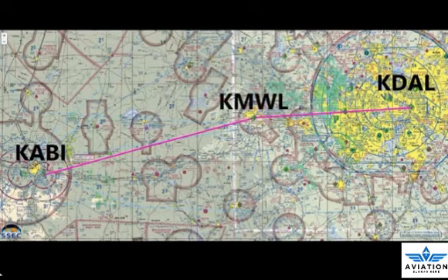Before taking off from Love Field, the pilot receives a current altimeter setting of 29.85 inches from the control tower, or ATIS, and sets this value in the altimeter setting window. When over Mineral Wells, assume the pilot receives a current altimeter setting of 29.94 inches and sets this in the altimeter window. Before entering the traffic pattern at Abilene Municipal Airport, a new altimeter setting of 29.69 inches is received from the Abilene Control Tower and set in the altimeter setting window.